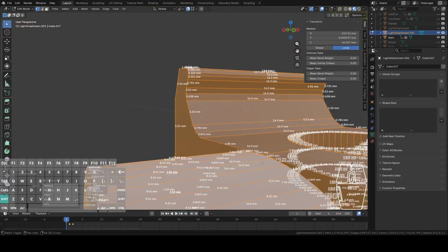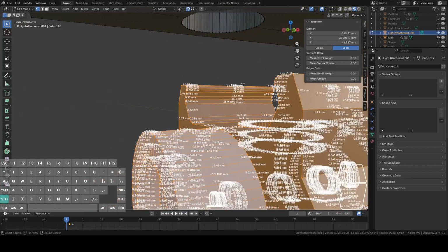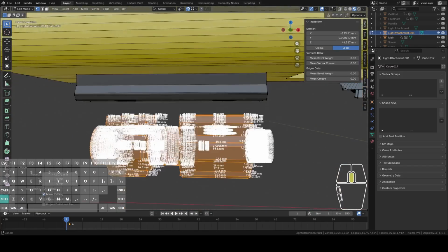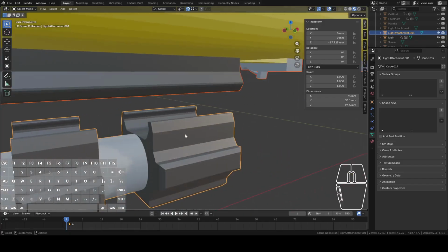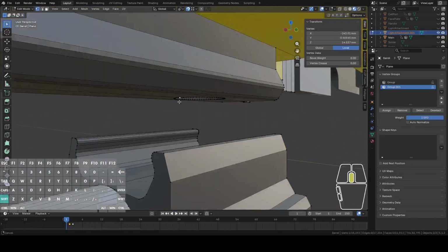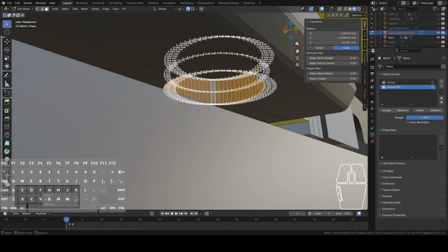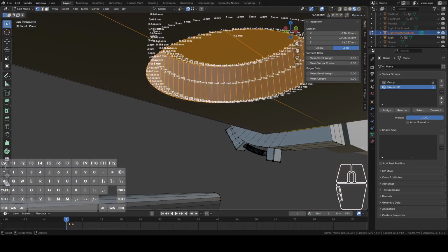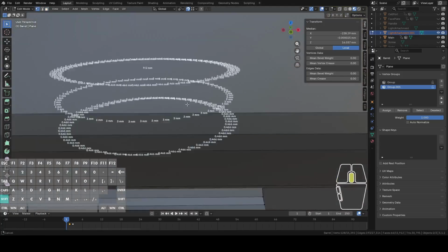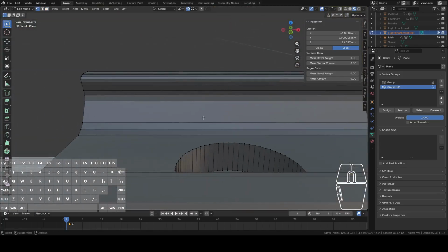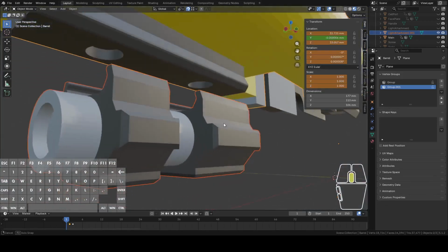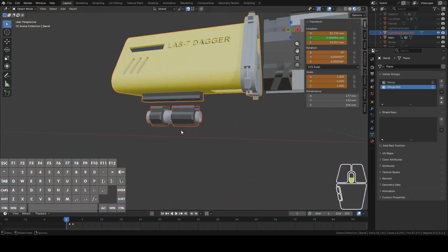So with this center point as our active, we'll snap it to this center point with GX. Should get all those. And now with those in place, let's get this guy again. All these faces, go back into vertices, this center point as our active, and we'll snap it with GX onto this center point. And now those magnet holes should align just fine.